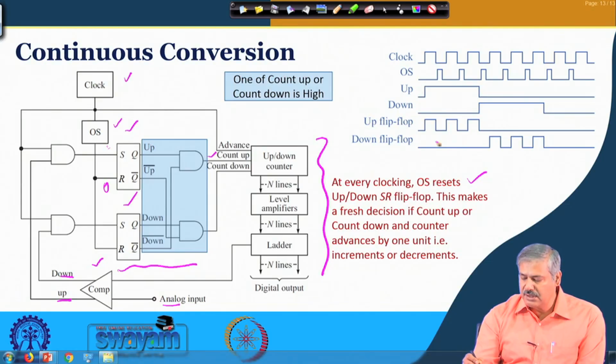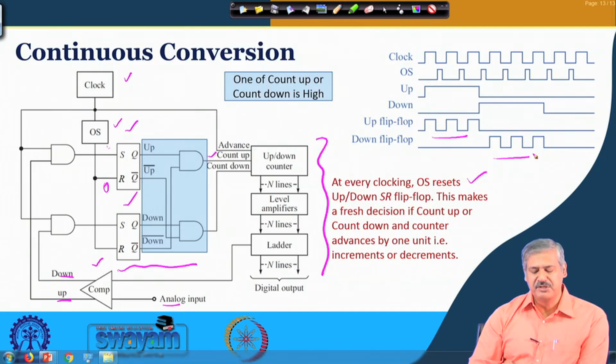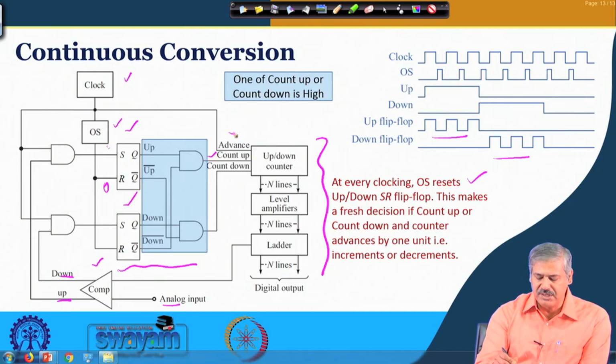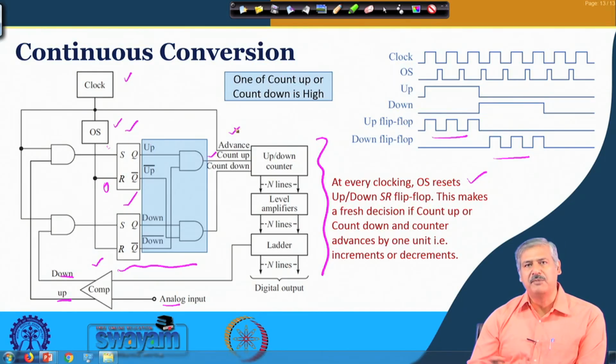So, this is up count is happening, and then again it is down count is happening based on this flip flop value, and every time the clock is coming over here and it is continuous looping. So, this counter is not getting reset. Is it clear? And this is the DAC output and this is the final digital output.